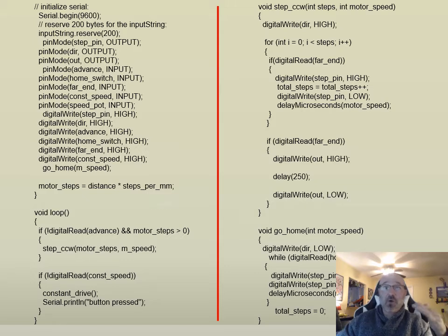We need to set signals from low to high, because a lot of that signal that's coming out of these is just going to be a TTL or a square wave that comes out of it at a known amplitude and voltage. And from that there, we'll say, okay, when I see this go high, I'm going to do the next thing. So maybe reverse the direction of the motor, which way the motor spins. It might be stop motion. It might be send out a signal. So all that's important. So that's where our coding here, where we start talking about some of these if-then, and these loops are going to come into play as we're coding in our electronics to take into account all these sensors in our closed loop system.